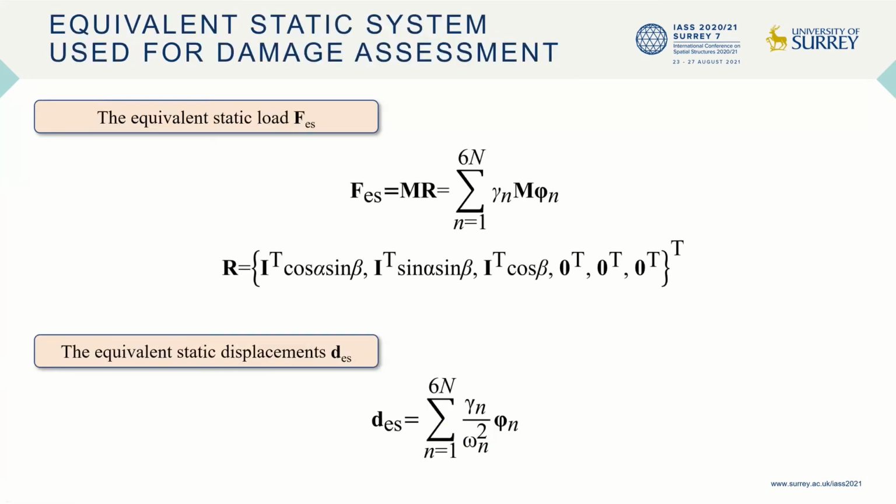In this paper, the damage index is established based on a specially designed equivalent static model. In this manner, the contribution of each modal damage to the whole structure can be tracked dynamically with the accumulation of seismic damage. Based on the modal pushover analysis method, the equivalent static load and the corresponding equivalent static displacements can be derived as shown.